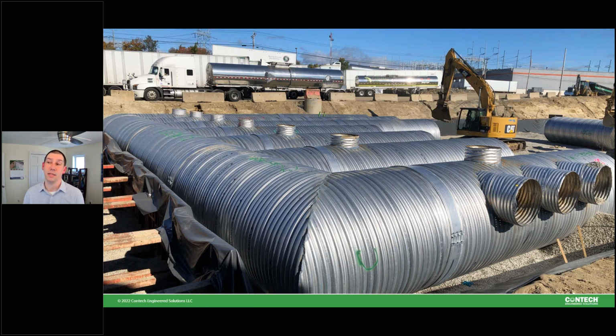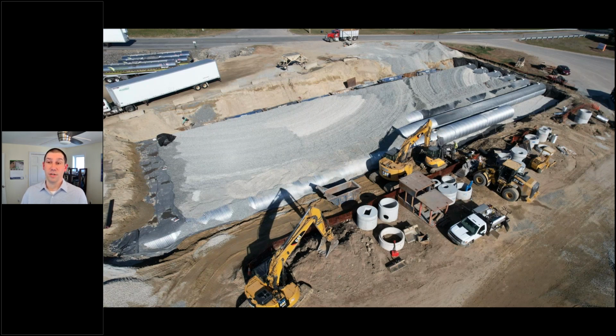We were able to meet the timeline because we already had the coil on hand. By building that manifold first, we could get it to the site before the perforated coil came in, getting the contractor started that much sooner, which was certainly helpful for the contractor in general. And as you might see, those last three barrels coming out high, those three stubs, are for the 50-year event, really looking at a spillway that went to a riprap channel that ultimately ended up inside a wetland area.